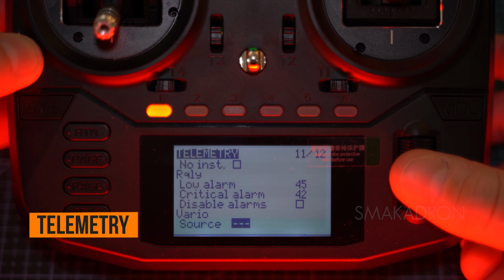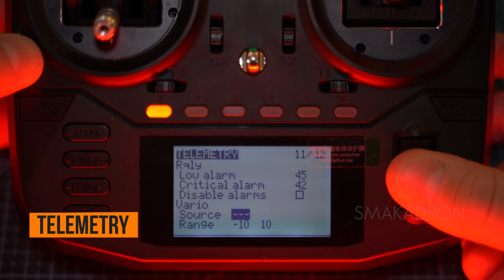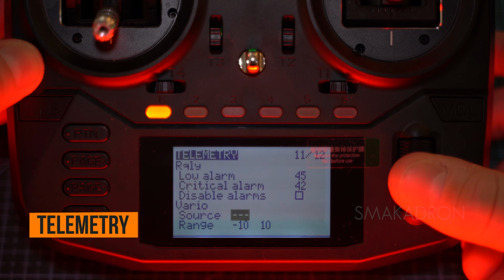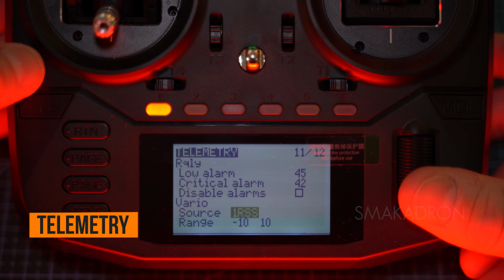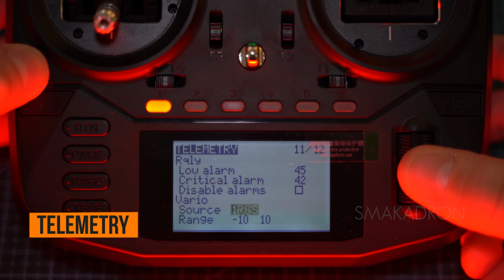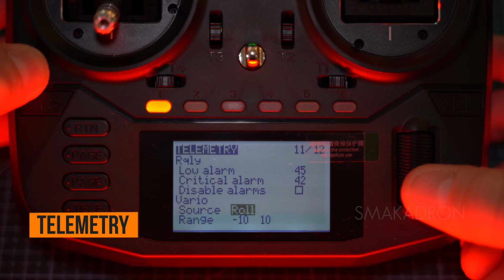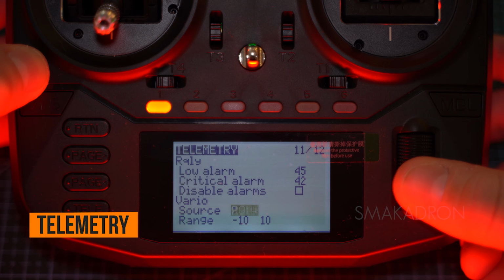EdgeTX can notify the user of these altitude changes by providing sounds with increasing or decreasing pitch. Use the variometer menu on the radio setup page to set the actual frequency and volume of the sound that will be played. The following options are available for configuring the variometer alarm. You will need to use the special vario function or a global function to enable this functionality.